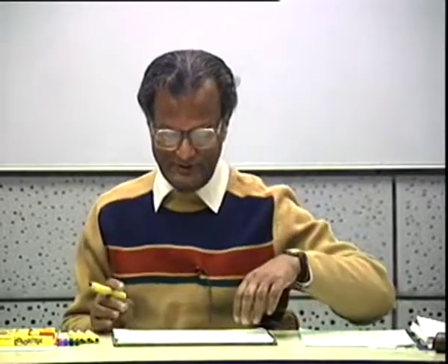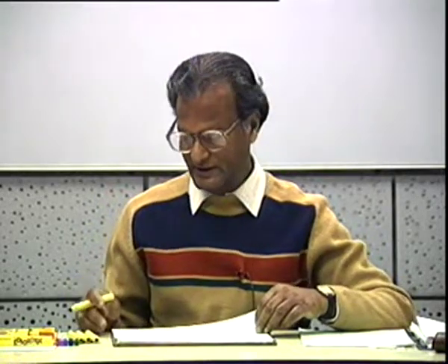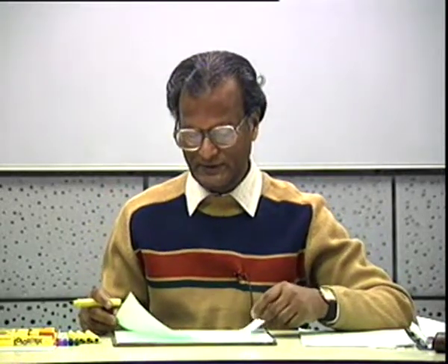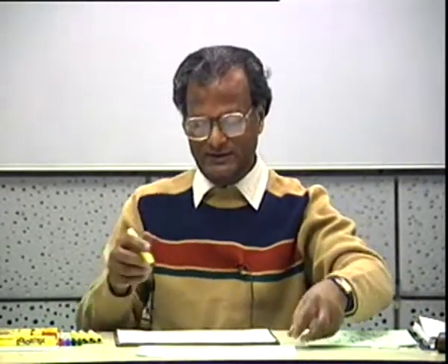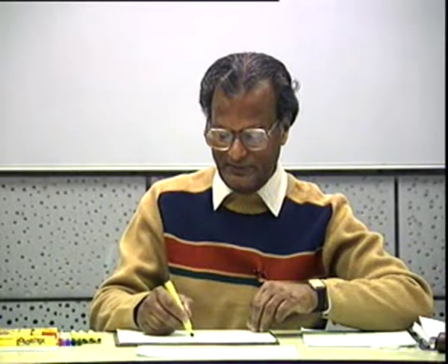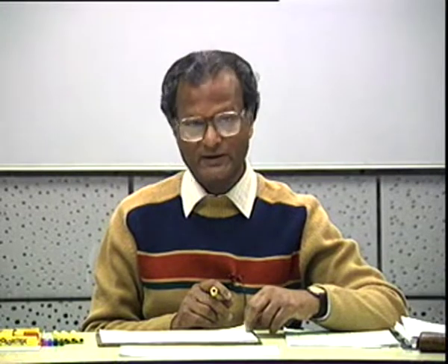Session number is 24th today, and we are going to discuss the use of current mirrors in differential amplifiers. This discussion had already started. We wanted this REE to be replaced by a current mirror because we could not use REE indefinitely in a lumped form because of two difficulties. One is difficulty of fabrication in integrated circuit, and the other is difficulty of increasing what?